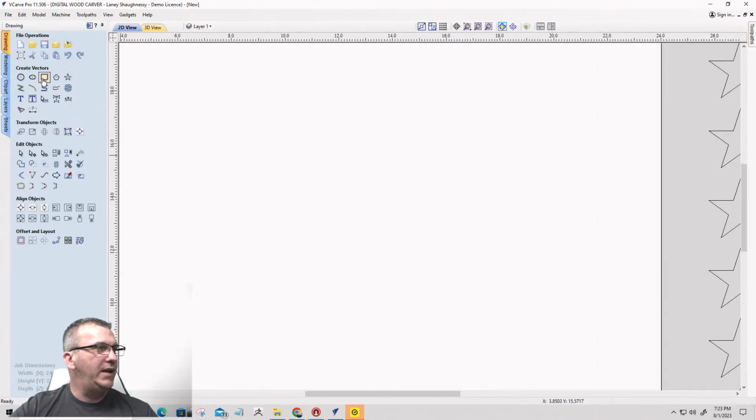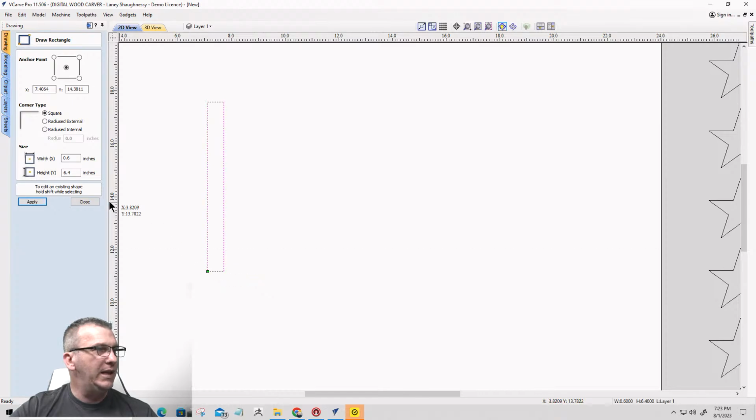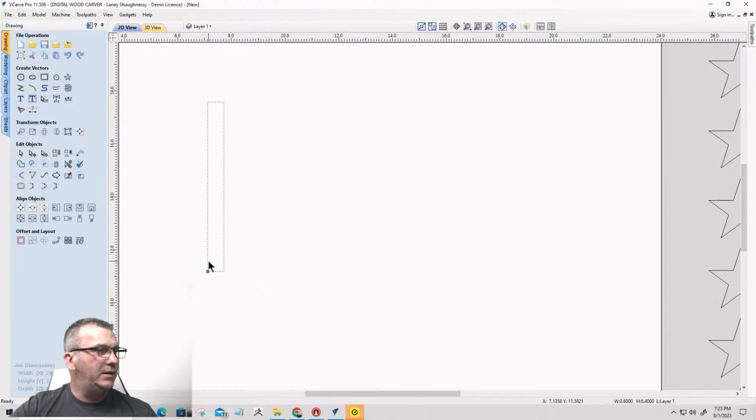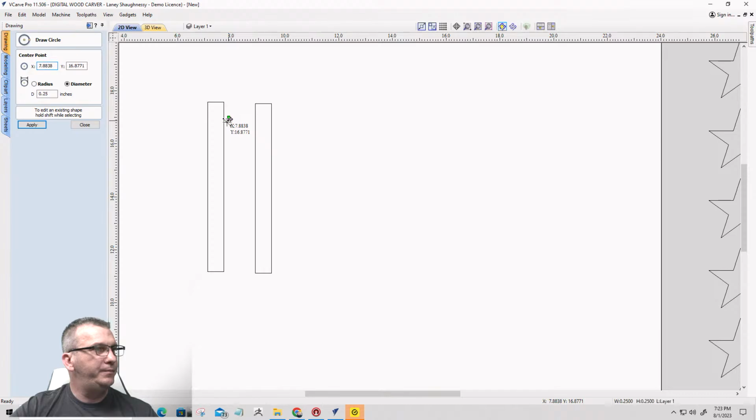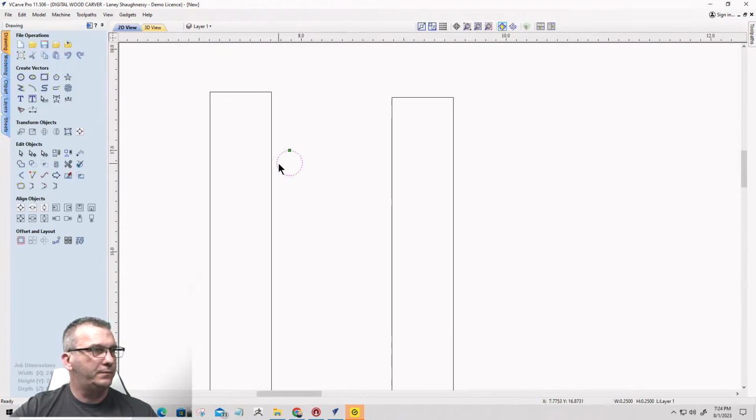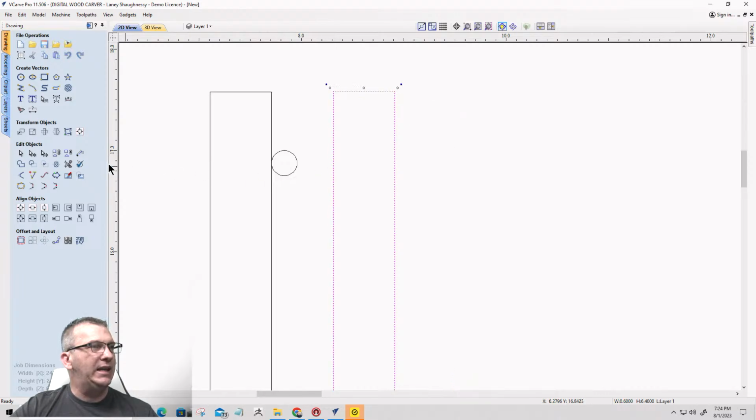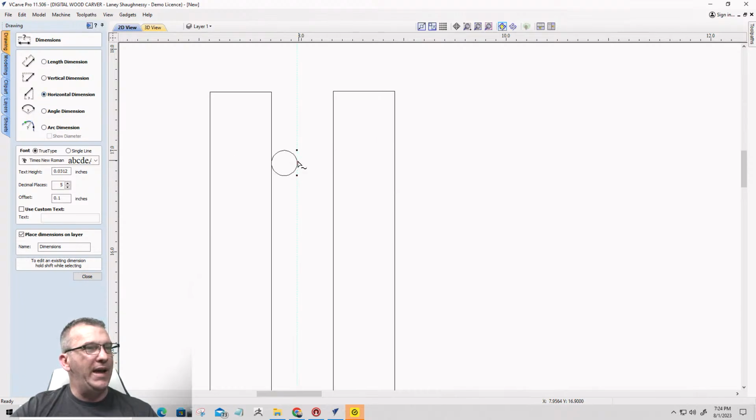If I have a part that I'm cutting, and let's hold down the control key and drag this over here. And I have my bit cutting. Let's say my bit is cutting up against the edge of that wood. And we'll move this over a little bit. But the clearance is the distance from the back side of the bit to the next part. That is the clearance in the nesting toolpath.